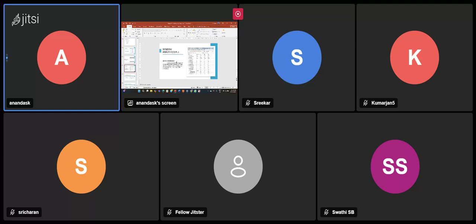Okay, so statistics window, as I already mentioned, serves as a numeric display of frequencies of data, remote error, and overload frames, bus loading, and also displays the state of the CAN controller. As you can see in this statistic window, bus load, and then you can see the remote error and overload frames. So that is the purpose of the statistic window, but we haven't used it much. But this is a very useful window where some projects may check this error frame or bus load.